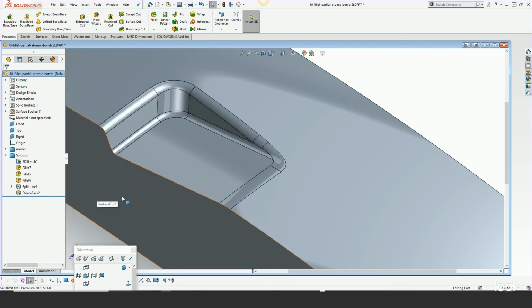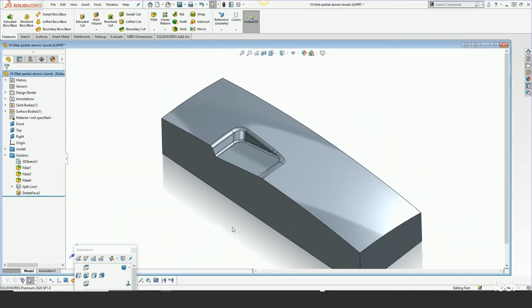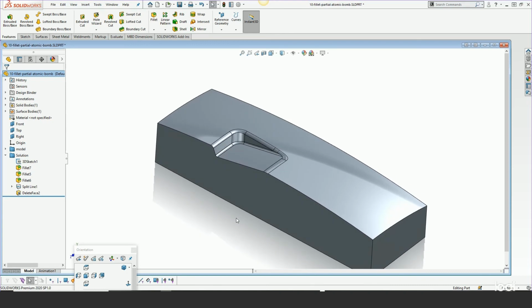I try to avoid going from solid to surface to solid, because when that occurs, you're passing along the body ID to a surface ID and then back to a body ID. That can make features fail down the line, especially the split feature, the save body feature, and if you're inserting bodies into other derived bodies, it'll certainly fail.